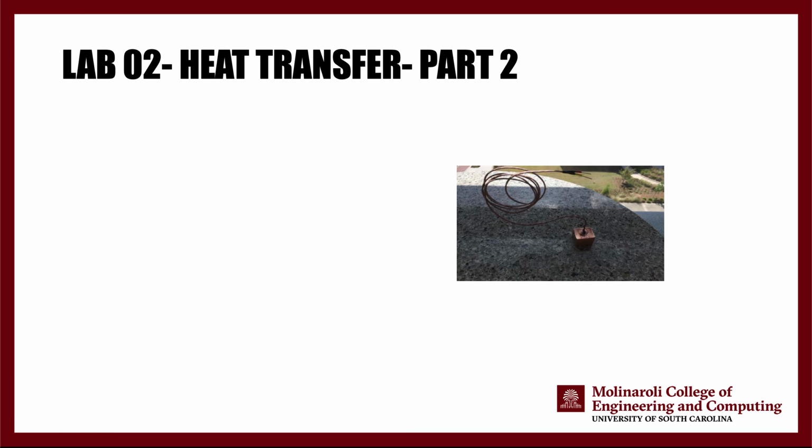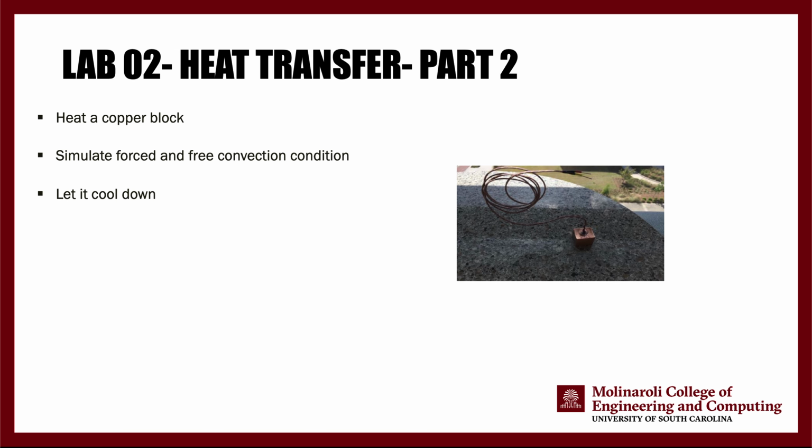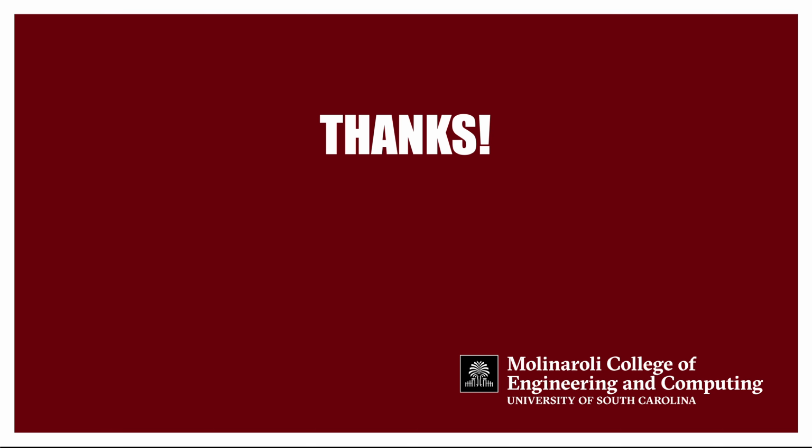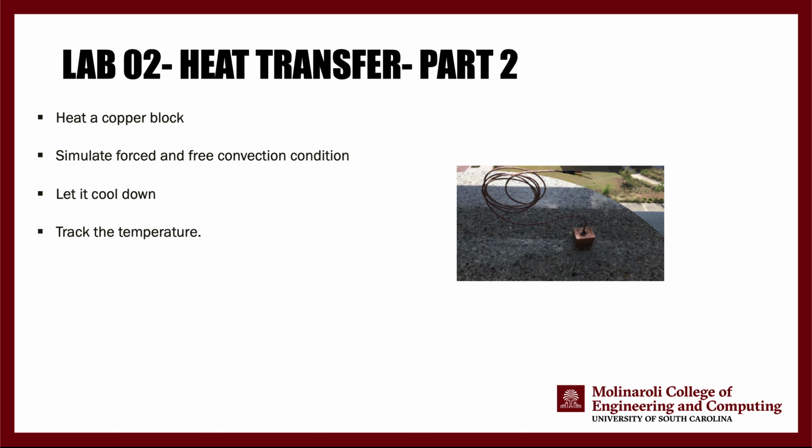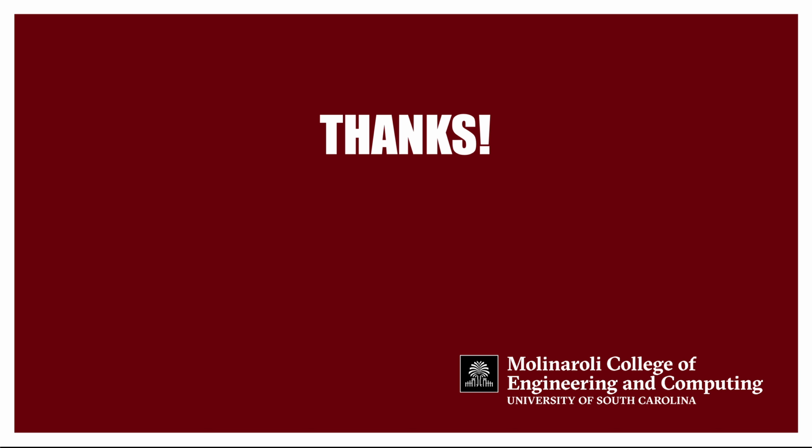Second part of the test is pretty simple. You will be given a copper block that is connected to a thermocouple. That thermocouple is connected to a DAQ. You heat it up, then you simulate force and free convection. You let it cool down in front of your fan or freely, track the temperature, and then eventually measure the heat transfer coefficient. Again, a statistical analysis must be done for this lab as well as other labs.